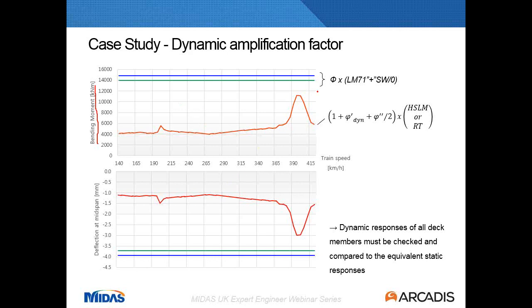And then in the same graph, plot the results for the static analysis multiplied. This is static analysis multiplied by the dynamic amplification factor. So in this specific case, this static load case and this factor is most onerous, so you can use that for designing your bridge. In other situations, your dynamic results might be most onerous, then you have to use them to design your bridge.